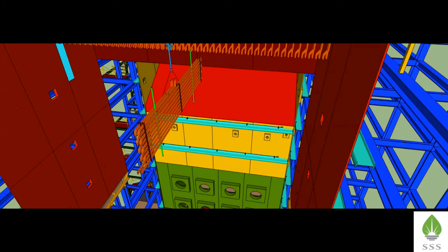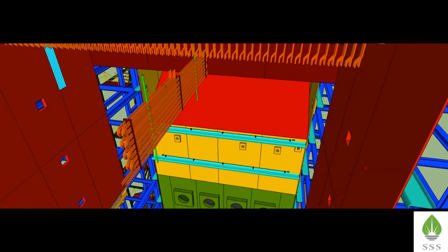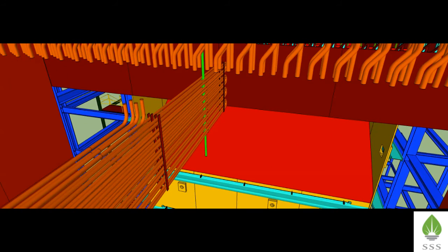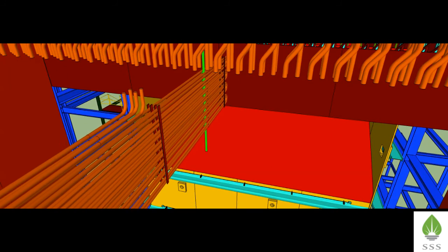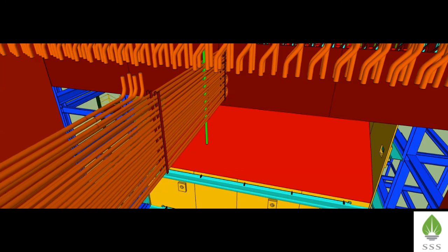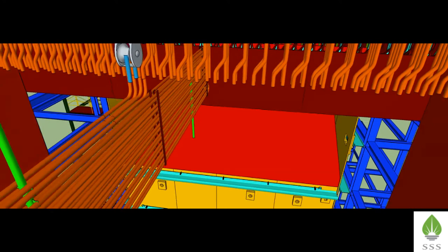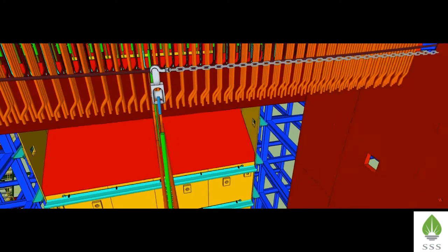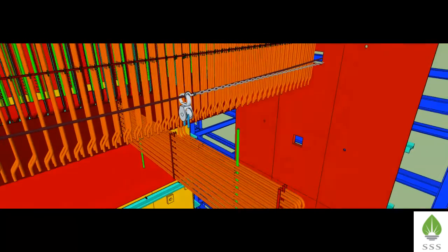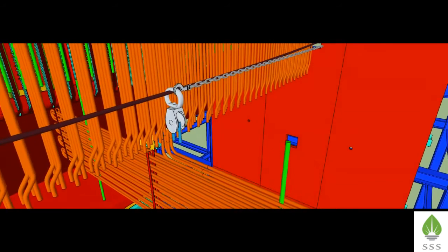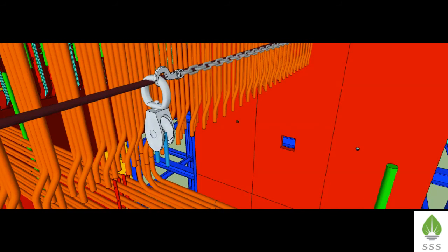Erect the coil to the position and weld the same with the vertical tubes which are seated previously. Also weld one end of these stinger tubes with the stinger tubes which were erected previously. Rope puller is attached to the pulley which aids in horizontal movement of the pulley for erecting another set of coils.